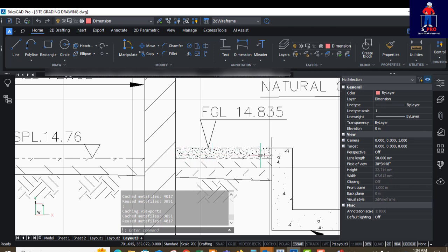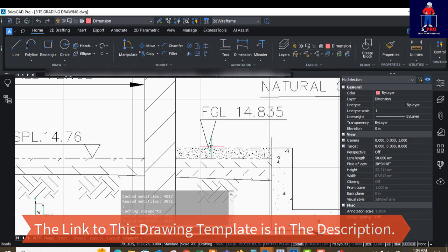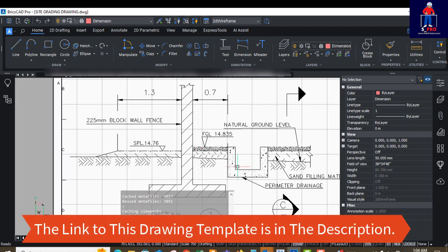What we normally specify for this finish is maybe some lean concrete and chippings. The concrete there is for anti-weed, so that if you have a plant like this, grasses will not begin to grow in your plant. So anti-weed will be there to make sure that grasses don't grow. Then they can finish it with chippings. Then after that we have our drainage before we now see the site itself. You see, natural ground level is what this line is showing us.